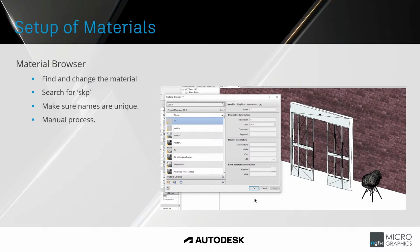Alright, so now I want to look at the materials, because that's a big thing, obviously. How Revit works with the SketchUp materials is it looks at the naming of those materials in SketchUp, and it brings it in as a material within Revit. As you can see here, you've got a couple of oddly named materials.